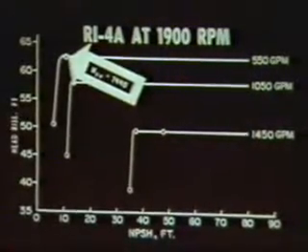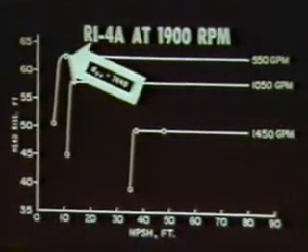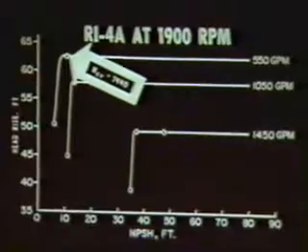The localized cavitation at the leading edge on the suction surface is indicated by arrows. Stall is evidenced by the forward-swept cavitation formations at the tip section.